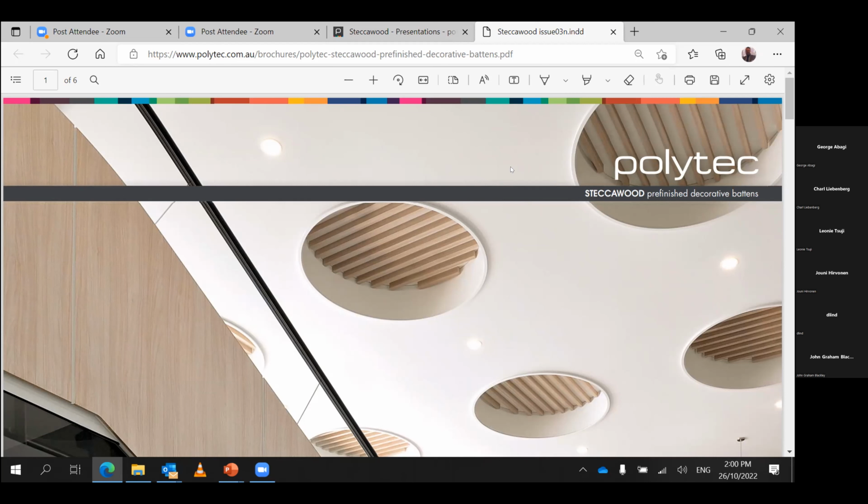This is not melamine. It's a hybrid of a foil system, quite good, quite hardy. It gets used a lot in different areas. It's not structural, so it's only MDF. It's moisture resistant MDF, environmentally friendly. It is currently available in group 3, so if you're going to use it in a foyer, it's going to have sprinklers. We can get it in a higher group rating. We just need to know about it to be able to make it.